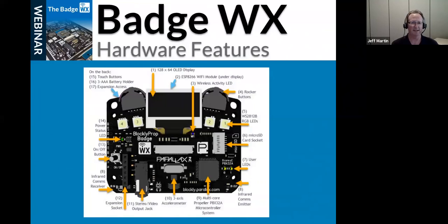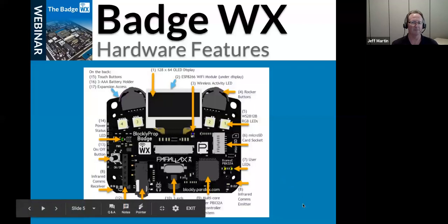It does a couple of checks and runs a menu system that you can use to see where it's connecting to Wi-Fi, and if it's not connecting, you can use the navigation buttons to manually select an access point and enter the passphrase. In addition, you could put a little Wi-Fi.txt file on the SD card with the name of the access point and the passphrase, and it'll start up, read that file, and attempt to connect to that access point.